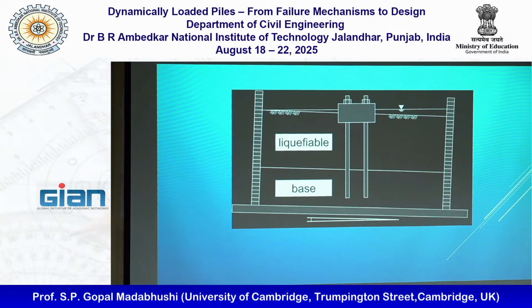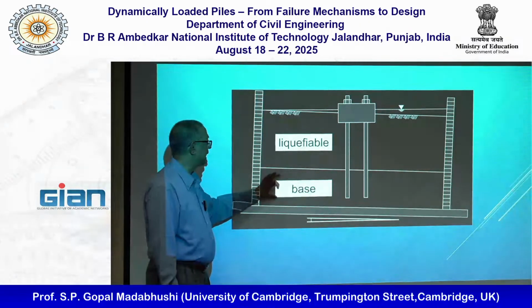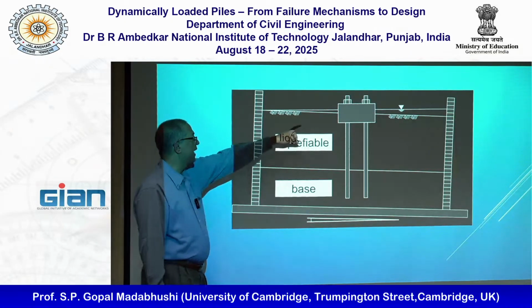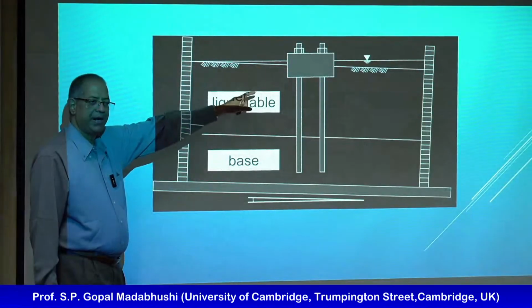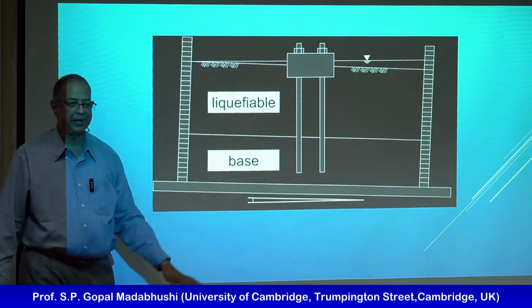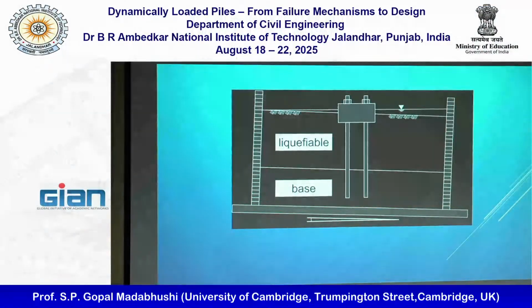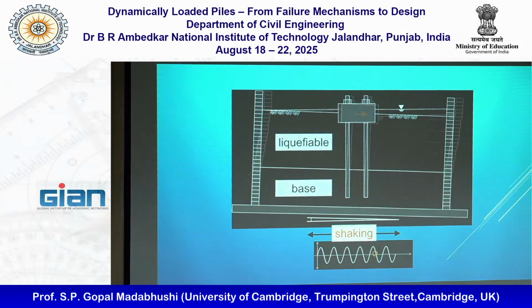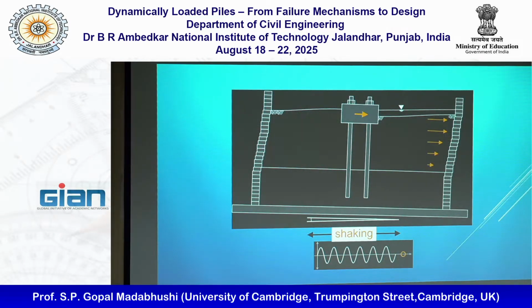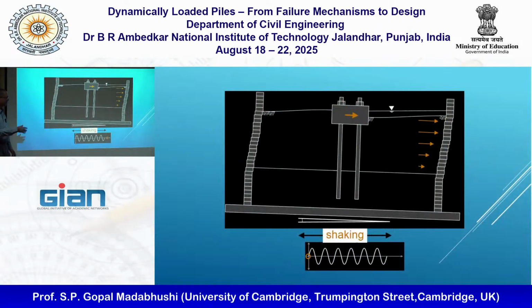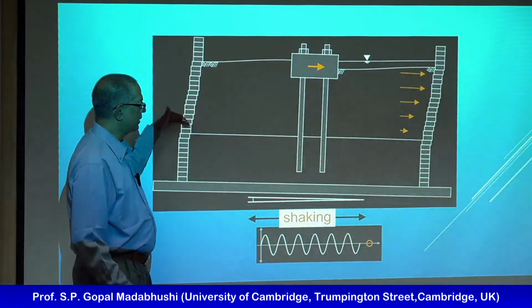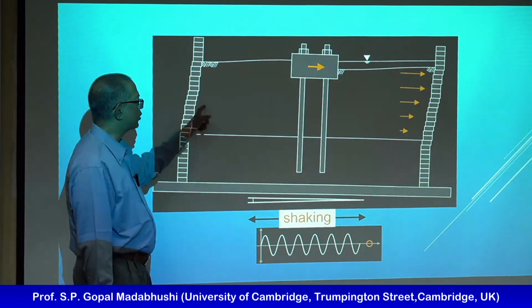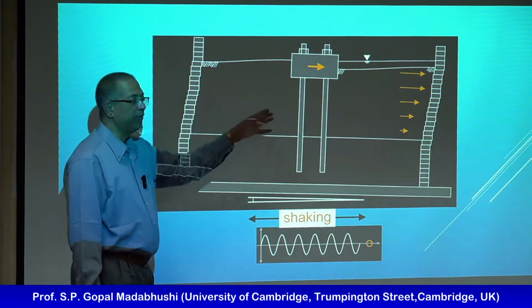So you've got some base layer, which is dense sand, and the liquefiable layer. In this case, our pile cap is always embedded into the soil. So we are not worried about the settlement issues like what I've shown you earlier. So when I shake, at the end of it, it will do that. This is an animation she created, but I can show you pictures afterwards. Basically, each of these rings can slide on the next one, which means if the soil wants to go there, this will simply follow it.